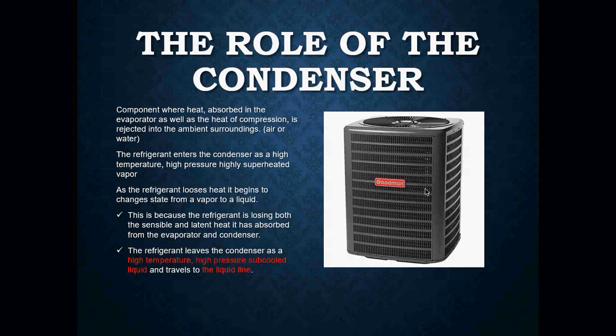Okay, the refrigerant enters the condenser as a high temperature, high pressure, highly superheated vapor. So as the refrigerant loses its heat, because now air is passing through it, it begins to cool off. And when it begins to cool off, it changes state. It's going to change state from that high pressure, high temperature, highly superheated vapor to a high pressure, high temperature, subcooled liquid. I'm sorry about that. Subcooled liquid.